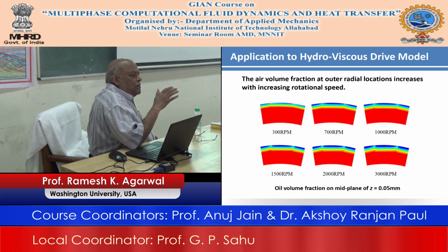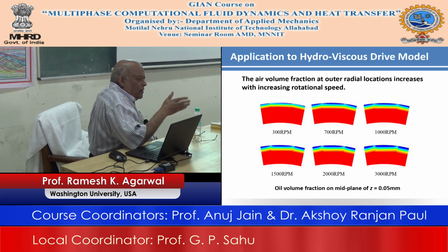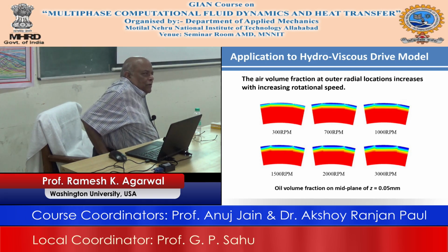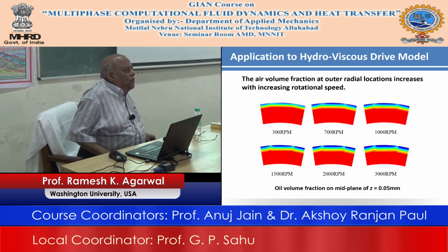So, step number 1 was to not even bother about cavitation, and whatever data you have without cavitation, match it. And the second step was then to consider the air and oil interface using the VOF, and this is a solution with the VOF, and it is easily doable in Fluent. I am telling you, it is very straightforward, and then you get this particular situation. Now, how do you then rectify this? Suppose you are a designer or you are a person who is working in the industry, then how do you rectify that?